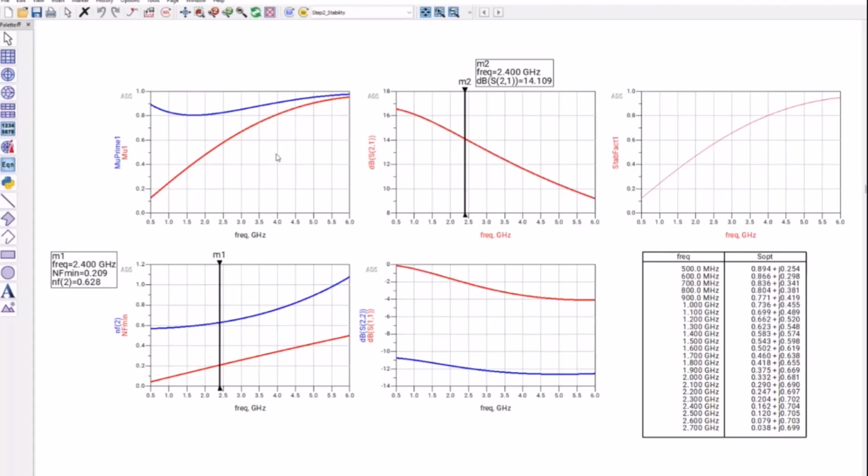So your design becomes very constrained, and there is a possibility that your amplifier can go into oscillation as soon as the wrong impedance is presented, or something happens. So it's a safer bet, as much as possible, to achieve stability over a wide bandwidth.